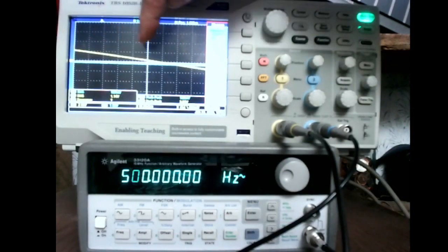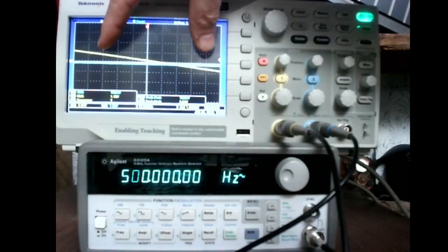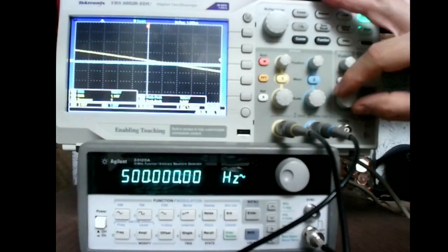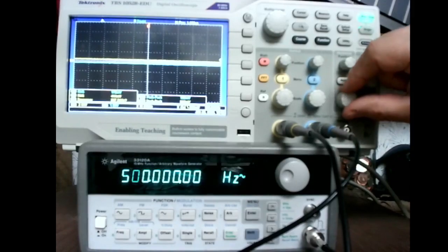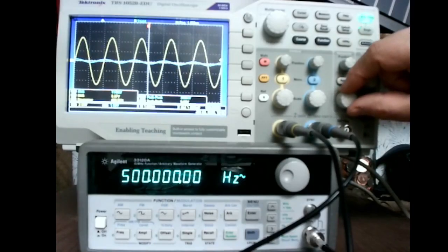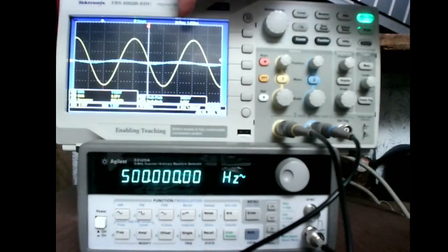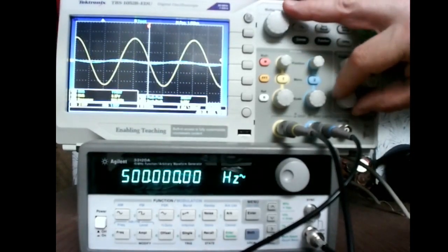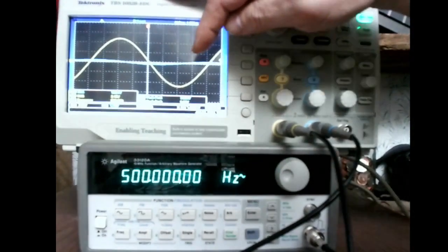Now what happens is that this is a way slower sine wave, so I'm only seeing a very small portion of my sine wave. So what I have to do now is on my scope, I have to adjust my time knob. I'm going the wrong way. Adjust my time knob to get the sine wave, so I can get like one whole sine wave. Like I say, I've got about 2 cycles of a sine wave here, but if I go here, okay, so here I've got one complete sine wave fitting on the screen.